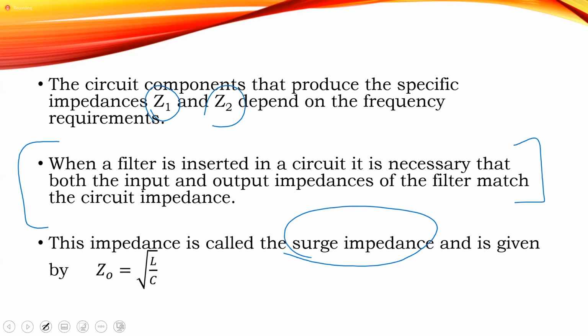The inductor would give me high impedance to high frequency, but low reactance to low frequency. So I then would put it in parallel. So for a high pass filter, it means that we'd have C in series and L in parallel. For the low pass, of course, it would be the reverse. All right? So do we have what's on screen?